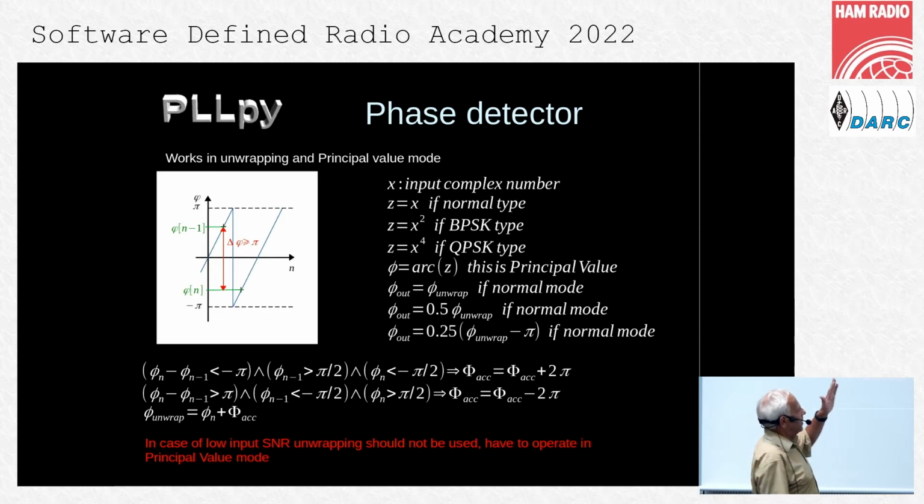Okay, I have had such an application where there was a transient phase error around 500 radians. That means it will track the input signal and won't slip any input signal cycle. That's a very important thing, especially if you have digital modulation.